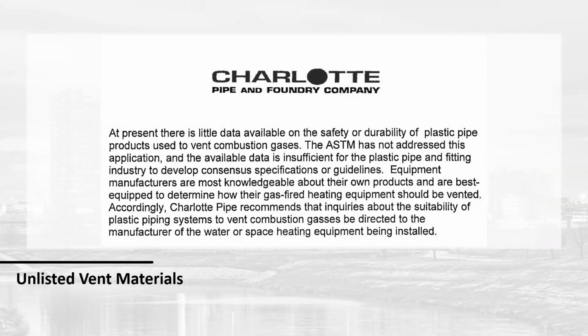There's, again, discussions back and forth, and this started in the furnace industry and has kind of made its way into condensing water heaters and is now slowly crept into the heating boiler systems. And it really all has to do with your return water temperatures. If you're doing a very low temperature system, you could probably get away with it and be just fine. But you may design a system to run at 80-degree return, and then the building does a slight remodel and they decide they need 120-degree return or 140-degree return, and now that vent system becomes a problem. So we always recommend using UL listed materials.